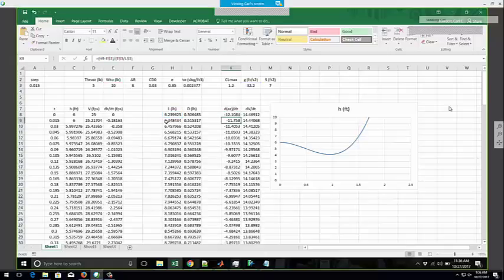So you guys have access to that if you want to look at this relationship and plug in your own numbers and see what that looks like. The other factor is, when reviewing these, it turns out this was adapted from a student who'd made some corrections, and adding this English second axis for the power loading was actually incorrect. The unit conversion was wrong. The conversion was based on if this had been watts per kilogram instead of watts per Newton. So I extended the graph range here and also corrected this side.